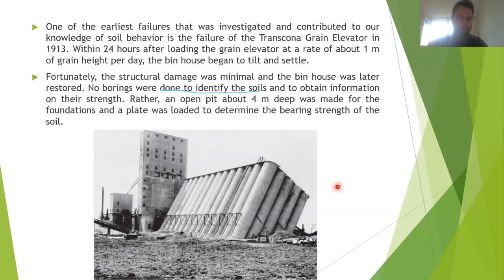The chemical properties are really important when it comes to the interaction between the structure and soil, because if you have acid soils they can damage your concrete if you're using plain concrete as you use every day. So basically, yes, I speak about soils in general because I'm mostly focused on the mechanical properties, because that's something you use in design.